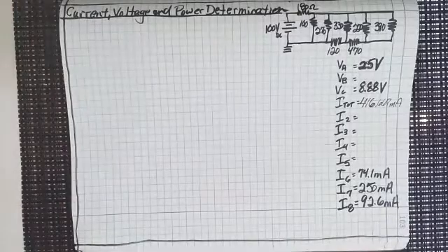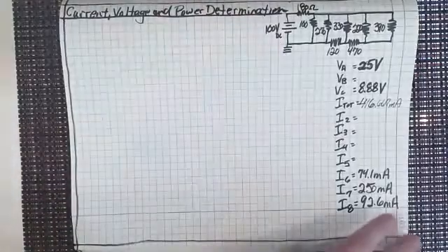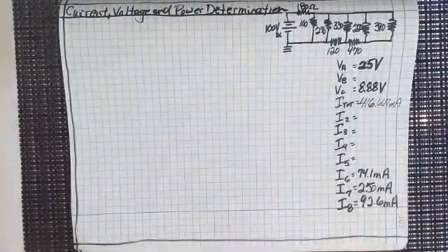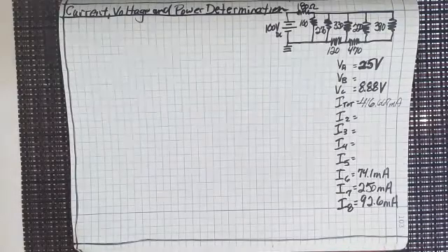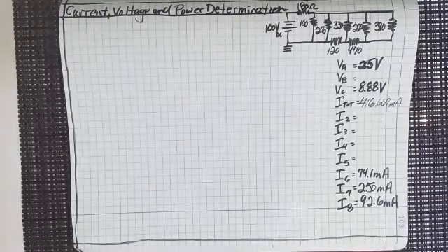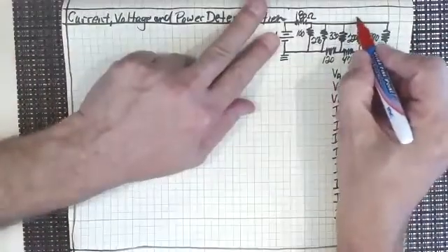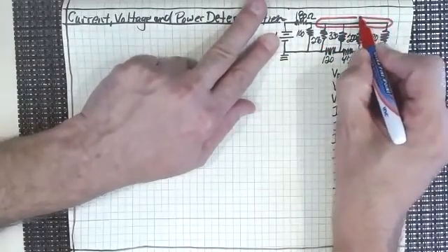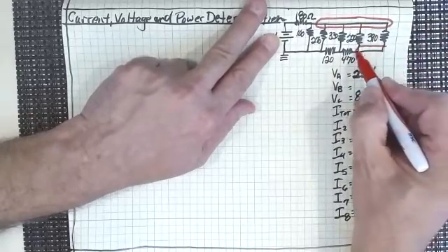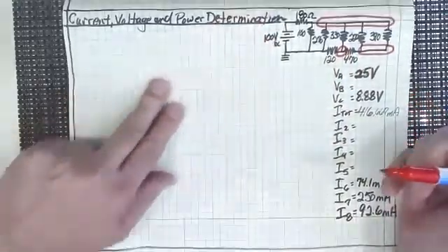What we're doing here is something that all electrical engineers have to do when they're learning the fundamentals of network theory 1: they've got to hone their skills at series, parallel, figuring out where nodes are, learning how to expand out a schematic from what you find on a printed circuit board, which of course is what we did with this, looking at the 3 nodes, applying Kirchhoff's current laws.